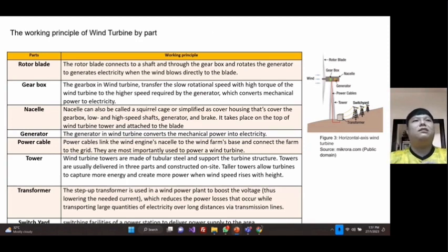The first one is the rotor blade. The rotor blade is where the fluid dynamics acts, which is the fluid flow over the blades with the velocity of fluid flow creating a pressure difference above and below the blade, exerting a net force and giving rotation to the shaft, where the Bernoulli principle applies, which means the faster moving air has the lower pressure.